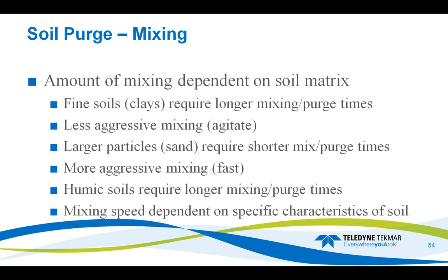We can also use more aggressive mixing in the case of larger particles such as sand, so you can use the medium or maybe the fast setting on the mixer. And then humic soils require longer mixing times in general because of the nature of the soils. They tend to vary much more from one to the next. That organic matter in the soil is going to change how it releases those volatiles to the water.